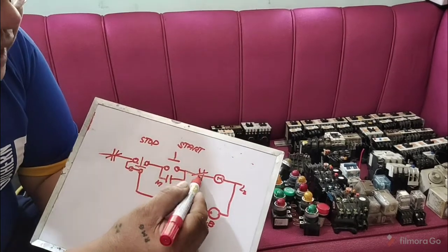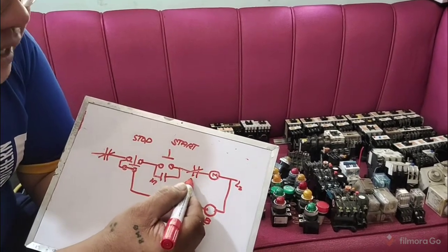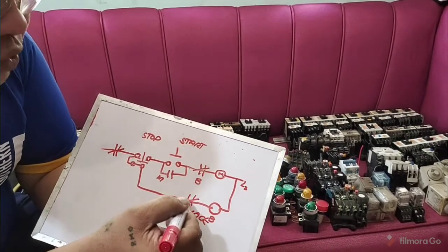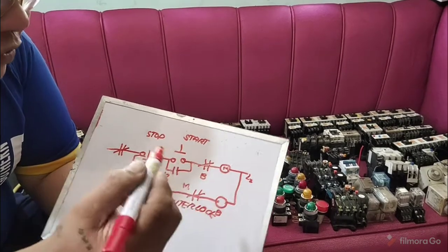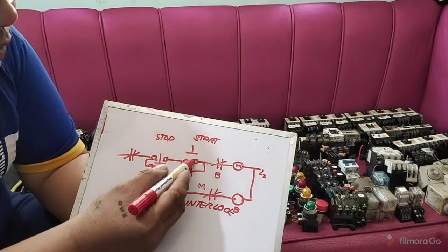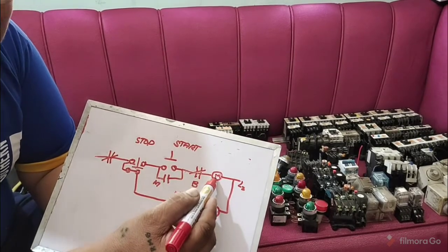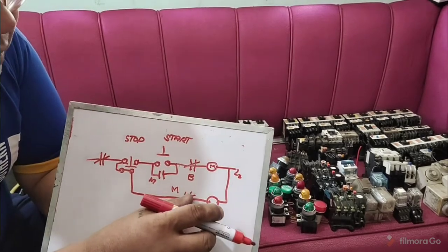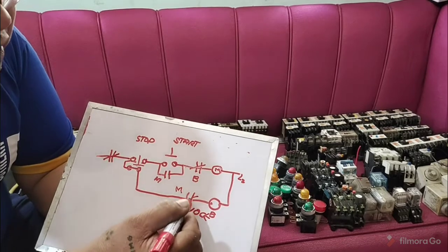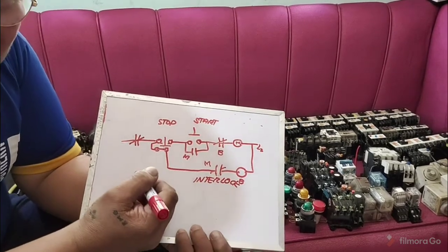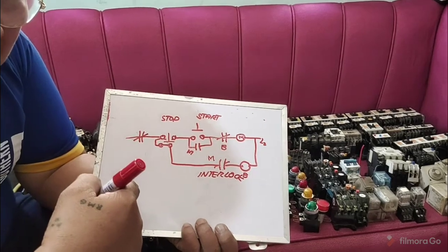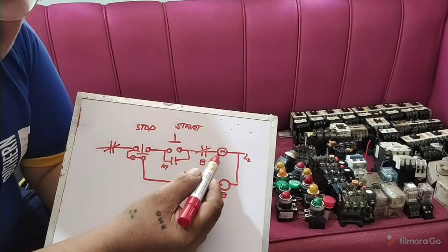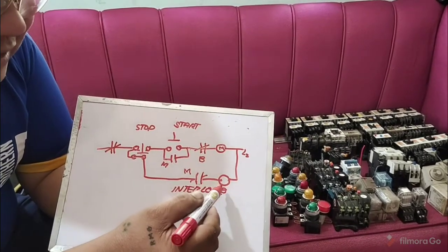So this one you have here is normally closed. This normally closed contact is taken from the brake contactor, while this one is taken from the M contactor. So look at this. When you switch on this one, of course, what will happen to the M contactor? It energizes, right? So when this is energized, what will happen to this? This will open. So there is no tendency that the DC, review your power circuit, while the AC is there in the motor, the DC will not.